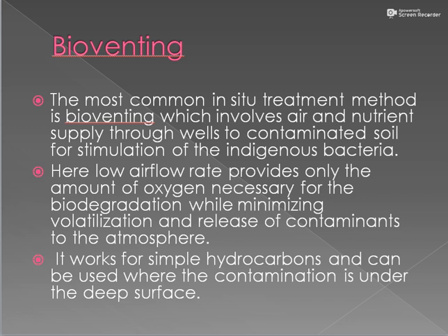This is an in situ treatment method. Here what you do is you add air and nutrient supply through wells to the contaminated soil so that the indigenous bacteria will be promoted to grow. Just remember, in ACs we do have vents, and the same way here in the soil you will prepare some vents, and through the vents you will supply air as well as nutrients into the soil so that the organisms capable of degrading the pollutant will grow there.